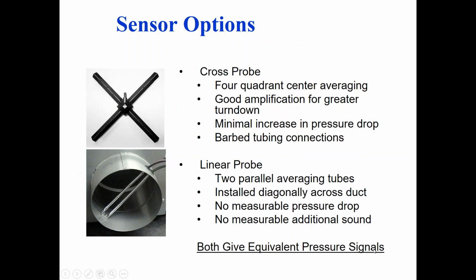On the inlet of the box, there's going to be a flow probe. His job is to tell us the CFM. He's actually going to measure static pressure, and we're going to tell him the inlet dimensions of the damper, and he's going to use that to calculate the CFM. And when I say he, I mean the VAV box controller that your controls guy is providing. Every controls guy is going to need one of these cross flows on here.